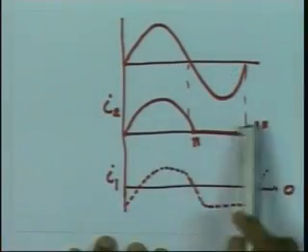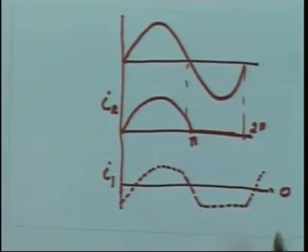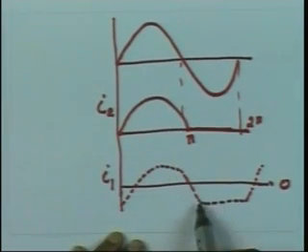The moment you keep it in AC mode, the DC bias disappears, you get a waveform symmetrical about the x-axis, and if you keep it in DC mode, the waveform with the DC bias will come on the screen. So same here, this waveform is what you can see in the oscilloscope with the DC bias. So remove the DC bias, I will get this waveform. So source current looks like this.